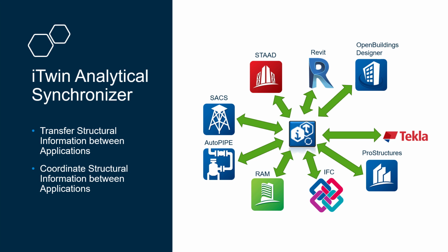Welcome to the Bentley Systems training course, where we will discuss topics about how to push a RAM structural system building model to the iTwin Analytical Synchronizer. In this particular video, we will create our new iTwin repository from an analyzed RAM structural system building model, including reviewing the push settings, specifying the deck and slab mapping, and choosing which objects will be pushed from RAM structural system to the iTwin Analytical Synchronizer.